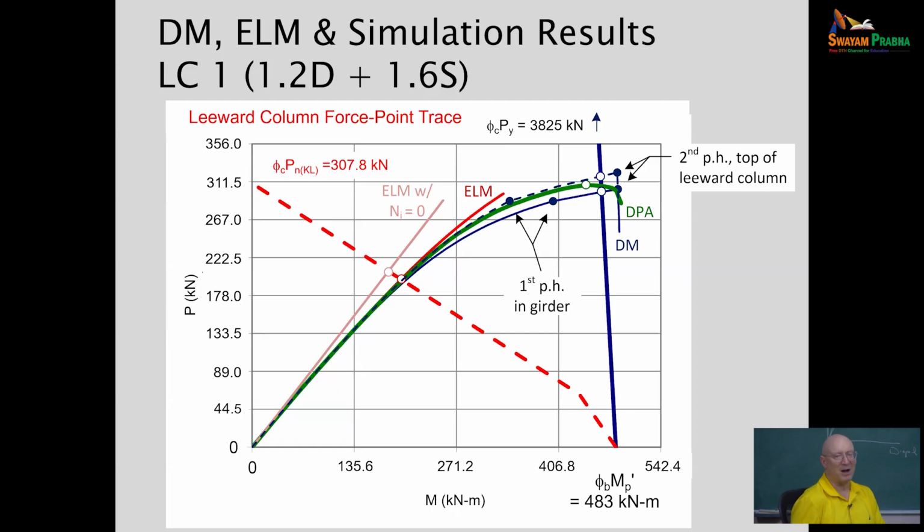We get a column strength for pure axial compression. So we get an anchor point. We say, oh, that's our anchor point for pure axial compression. So what's that representing? That's representing, again, if I had pure axial compression, just say put loads over the tops of all the columns, push it down, and I get to a point where I say, oh, I lost my column capacity, it goes. That's kind of more of a bifurcation problem. And then the approach with the effective length method is saying, okay, we're going to use that as an anchor point. Now let's look at the other anchor point.